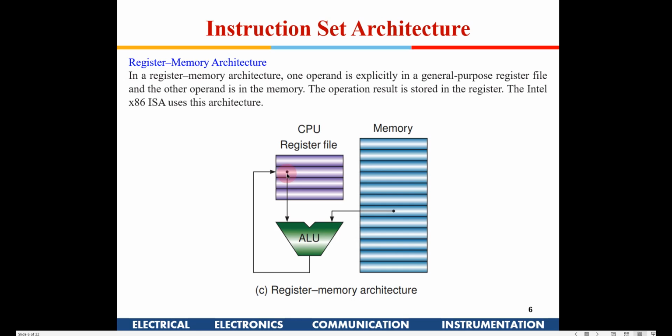When we discussed earlier, if you remember, the 2-byte ISA and 3-byte ISA, there were some advantages of a 2-byte ISA, and hence 8086 and these processors have one of the target data stored again in one of the registers. Like if I do A plus B, then A gets rewritten by the sum, whereas the contents of B remain the same, right? So one register will get updated with the result. That is how a register-memory architecture works.